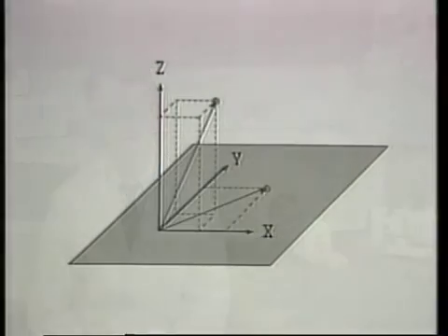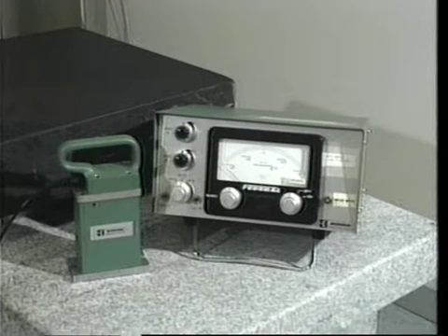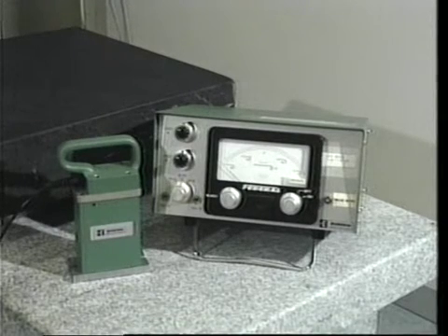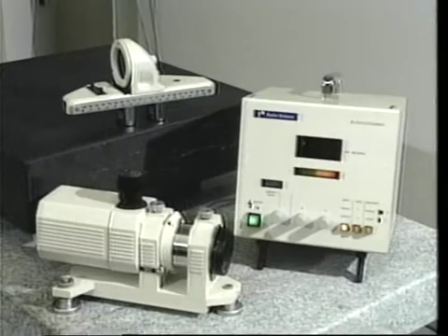The objective of this lab is to demonstrate surface mapping using the electronic level or autocollimator. Establishing a reference plane is often a prerequisite to measurement or fabrication procedures. Relative to this reference plane, points can be established either within the plane or outside of the plane. Measurement of a surface's deviation from plane is typically performed with an electronic level or an autocollimator.